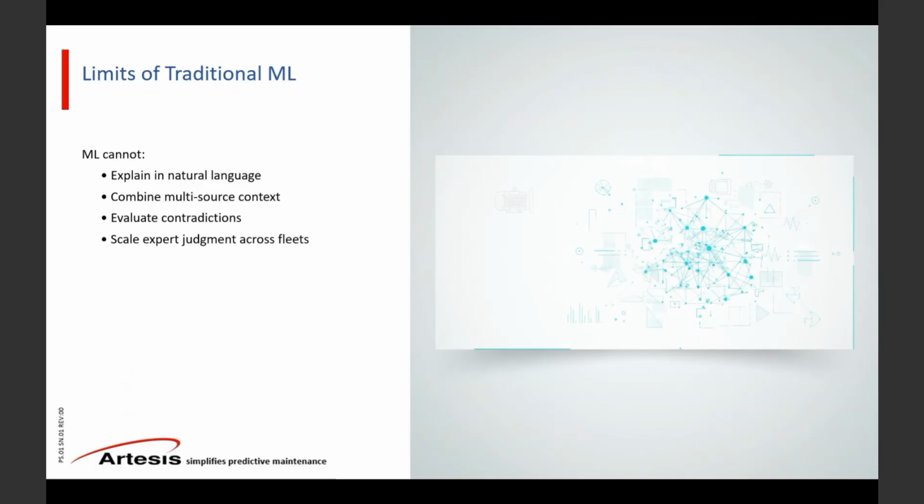It also doesn't automatically combine the multiple signals that our electrical signature analysis-based solution generates into one narrative. You will sometimes have mechanical issues. You would see a bearing fault, but if that comes from fluting, which is caused by a VFD, it requires a more comprehensive look into multiple data sources to, again, create a single narrative. In real life, you're not looking at one trend in isolation. You're looking at spectrum, operating conditions, load changes, and process indicators all together, trying to connect them into a single coherent assessment.